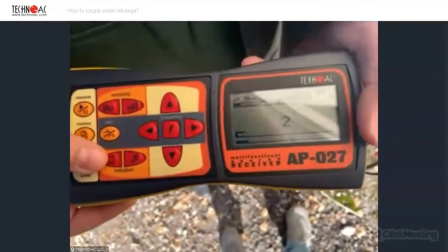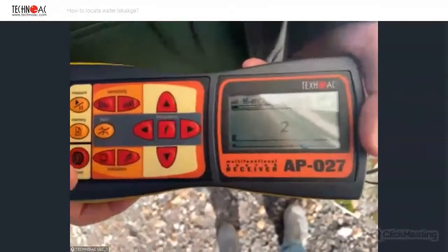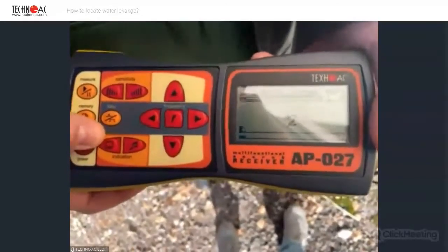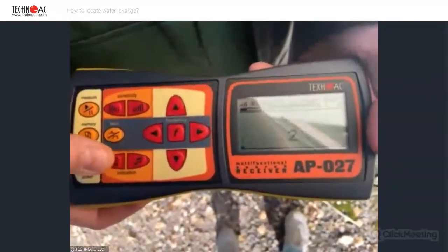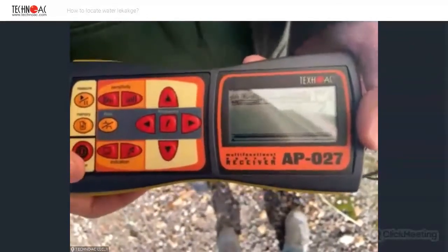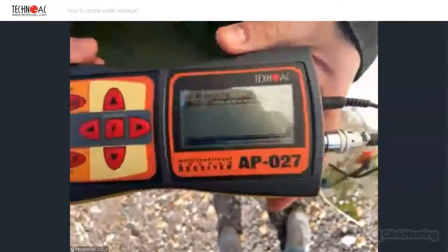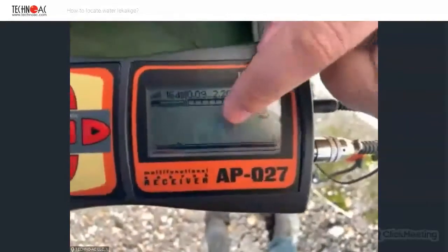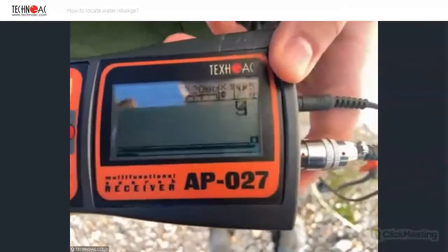That is why we will switch the visual indication of the device into spectrum mode. And I will press this little TV button or video indication button twice in order to enable the spectrum mode. This mode is represented by a scale which has filling bars. I will show you. Just give me a second, please.